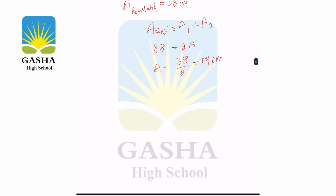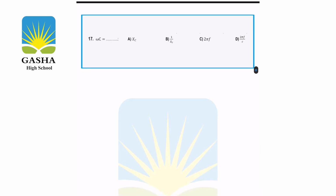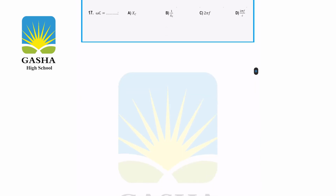Okay, question number 17. We have omega C, which is angular speed times the capacitance of the capacitor, equal to which of the following? You have to know that the capacitive impedance is inversely proportional to the capacitance of the capacitor and to the angular speed.